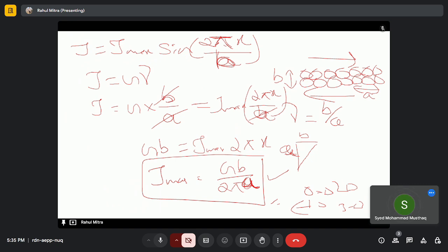If we talk about 2-dimensional defects, we have the free surface, the grain boundaries, the interfaces and other faces. And for 3-dimensional defects, we have inclusions, precipitates, other phase formations, etc. And the dominant mechanism of deformation is through dislocation motion.